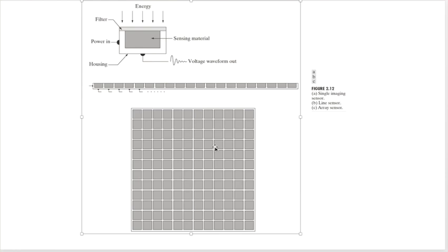What would happen if just all of a sudden, in the midst of that nothing, I made a charge carrier appear? It would flow, wouldn't it? It would carry charge. I'd be able to record that there was a current flow. So if I take a diode and I reverse bias it, and remember, what happens when photons hit a material? They knock an electron off. Right? That's called the photovoltaic effect. Yes? This is how solar panels work, right? And we just put them in a particular range that we wanted.